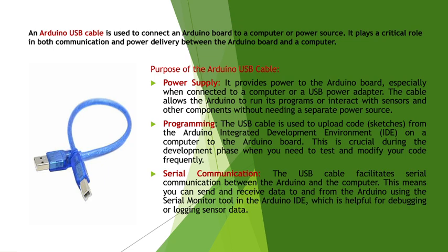Serial communication. The USB cable facilitates serial communication between the Arduino and the computer. This means you can send and receive data to and from the Arduino using the serial monitor tool in the Arduino IDE, which is helpful for debugging or logging sensor data.